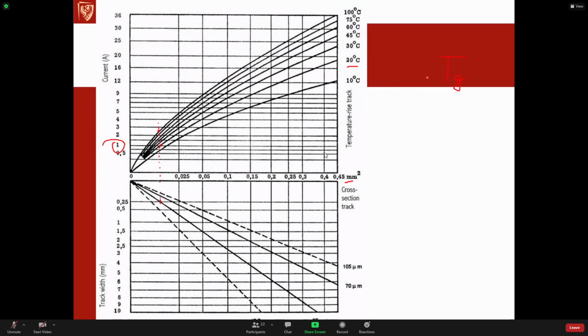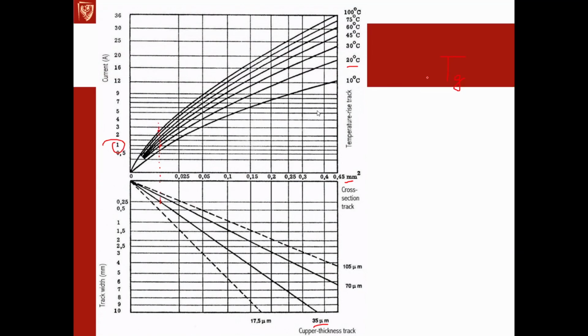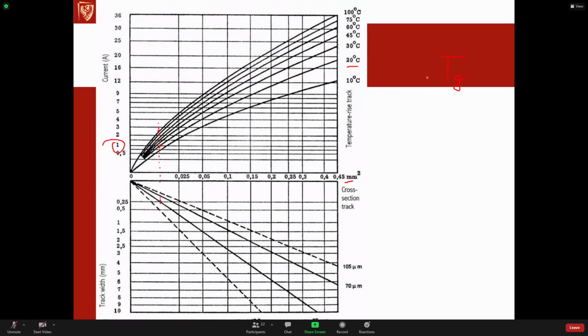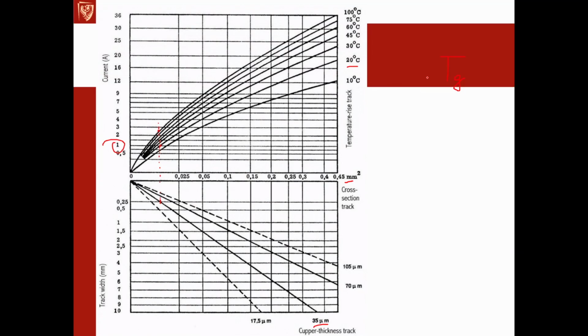I didn't see the comment first. One nanohenry is sometimes used in DC converters. Yes, it is. No, not really. One microhenry. About DC converters. So the answer to Jakub first, because I hadn't noticed the question. One nanohenry is not used in DC converters because it's too low for the megahertz range. Nanohenry starts to matter at gigahertz. So for high frequency we use only nanohenry inductors. For DC converters, we talk about microhenries and even millihenries, sometimes for low frequency DC converters.